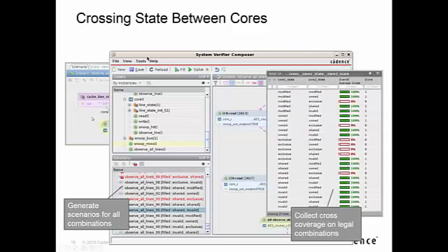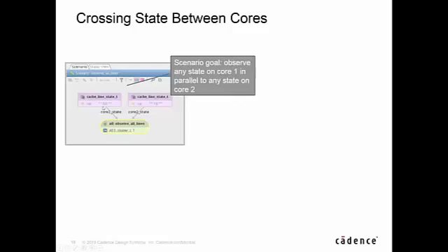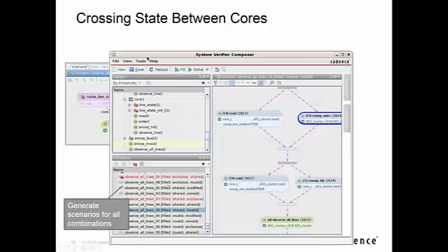So in this case, you see, oops, I go back here, we're actually telling it to fill in all the cache states. So we're not forcing a particular cache state, but saying we want a complete view, and it comes up with all the solutions to be able to verify all the different legal states. And the states that are shown here in red are the ones that are illegal. So it gives you a complete solution based upon what the legal states are, and shows you what the illegal states are as well.